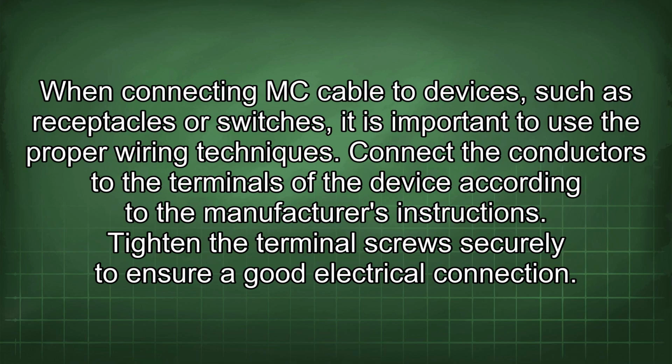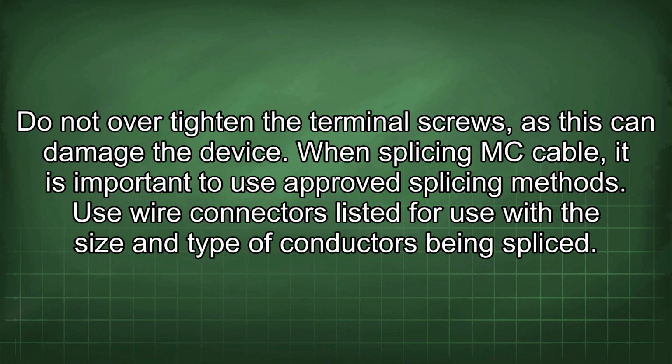When connecting MC cable to devices, such as receptacles or switches, it is important to use the proper wiring techniques. Connect the conductors to the terminals of the device according to the manufacturer's instructions. Tighten the terminal screws securely to ensure a good electrical connection. Do not over-tighten the terminal screws, as this can damage the device.